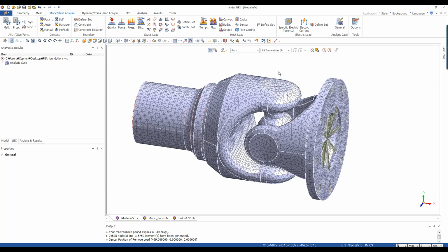I would like to explain that. If you imagine that you have two spheres and you want to perform a simple Hertz experiment, there is no constraint between those two parts at the contacting point, but we are looking for the reaction between them, and this is why we have to use contact, which will describe the proper behavior between those two parts. So this is why we are using the contact and the constraint. Let's say a kind of constraint will be created between them. So this is how you can start to think about that.